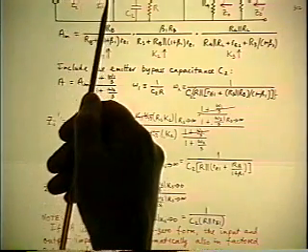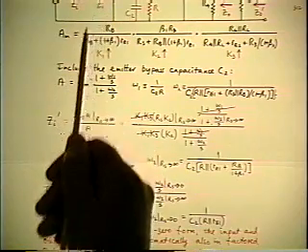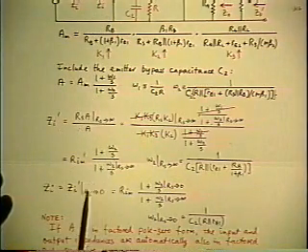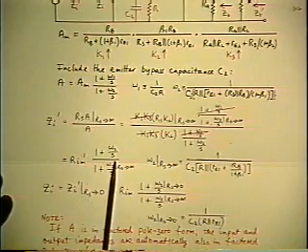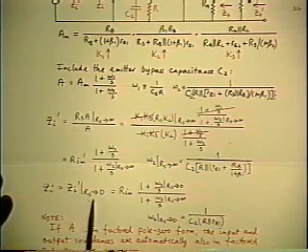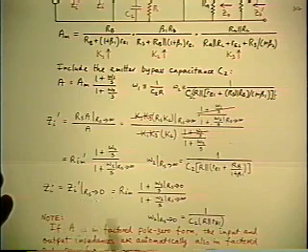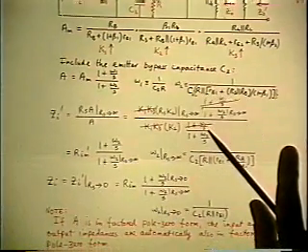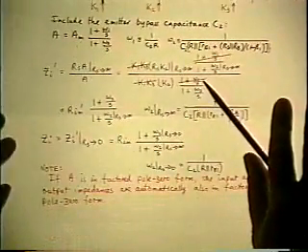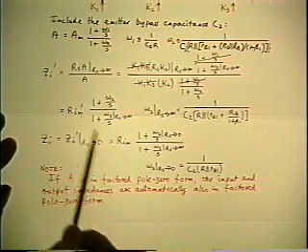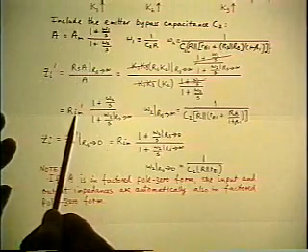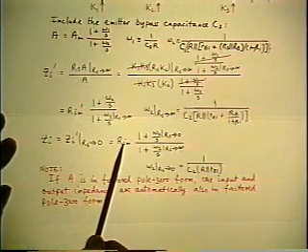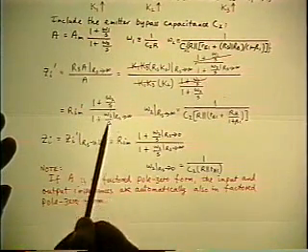Now, if you want the inside input impedance, you can take the other limit in the answer we just got for the outside input impedance. And again, you take the other limit, which is Rs goes to 0. You just do that, factor by factor also. The midband part of it we already did. Just takes away the Rs from inside the Rim prime. Leaves you Rim. Look at the two corner frequencies.